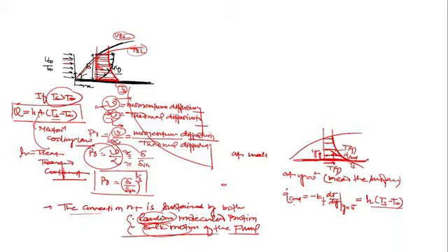Now listen, as I told you, convective heat transfer is strongly influenced by the flow field. Yes or no? Boundary layer phenomena are essential to understand convection heat transfer, and a boundary layer will always develop whenever the fluid flows over a surface. That's why I told you fluid mechanics plays a very important role in the analysis of convection. Why strongly? Because when I increase the velocity on the same plate, let's say this plate is hot at 100 degrees Celsius and the fluid flowing is at 20 degrees Celsius with a velocity of 1 meter per second, and I increase the velocity, the rate of heat transfer will increase. Yes or no?